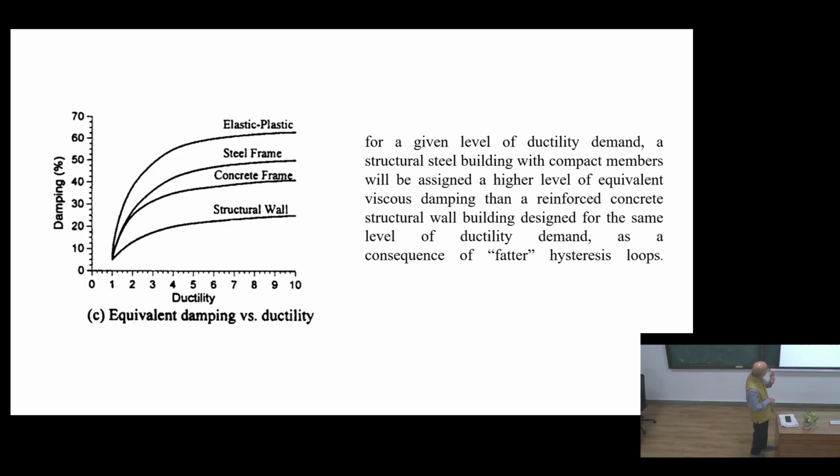Here I will speak just a few words. I did this for several materials, concrete and steel. You look at the ductility which you build into the structure and the material which you use for the structure, and how much damping, because damping is very important. Damping and stiffness are the two important parameters. Depending upon the material used, how much damping you get matters, because damping will help in damping the forces which are generated. That is important. Next slide.